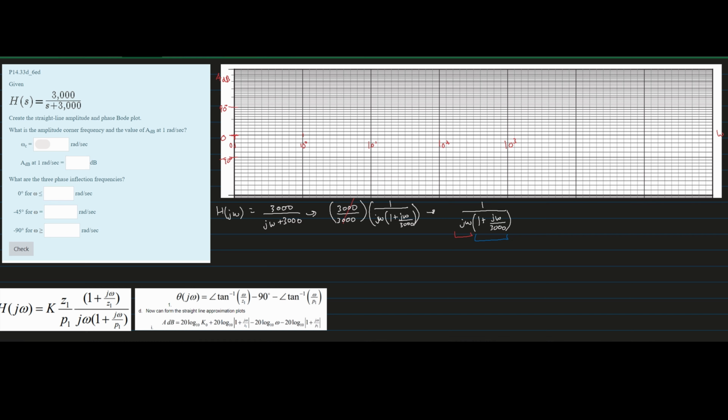Now this can be found in the notes linked below the like button, page 97, the summary of Bode straight line magnitude and phase plots. For this, we basically have 1 over jω, in parentheses, to the n. This n is going to really decide our slope. Since for this problem, like the previous ones, we only have a 1 in here, it's going to be 20.